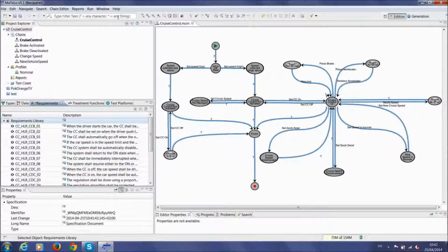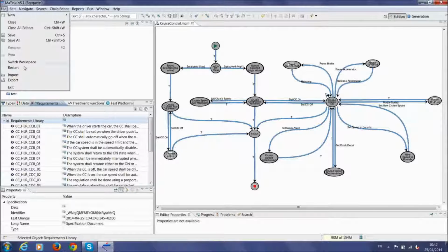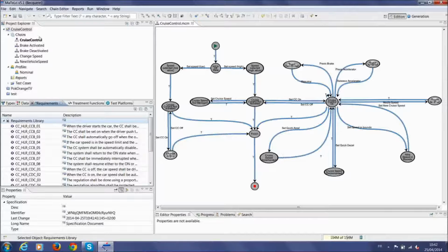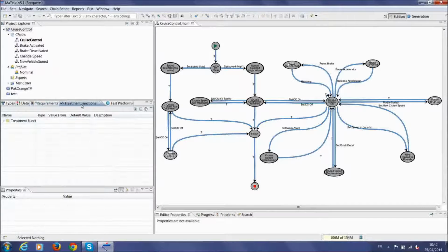A text field appears. To edit a new requirement, place the cursor on the Requirement Library folder, right-click and select New Child and Requirement Definition. A requirement name direct_name by default is created. To rename it, select the long name field in the Properties window and edit the name of the requirement. Modify the description of the requirement as shown.